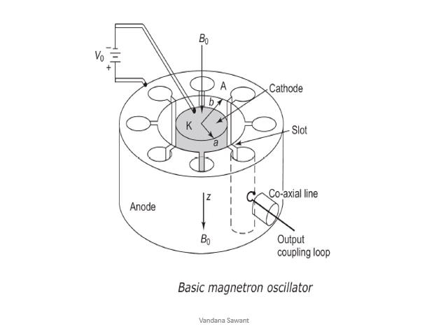Similarly, when we supply a high negative voltage to the cathode, the cathode will emit electrons. If you see, a V0 voltage is supplied between the cathode and anode, so that will make the cathode emit the electrons. That will make the anode reentrant cavities generate an RF signal. Similarly, it will generate an electric field which is transverse in direction.